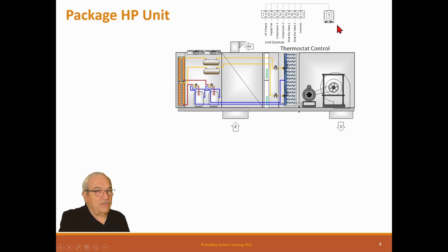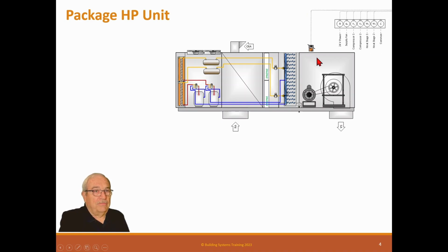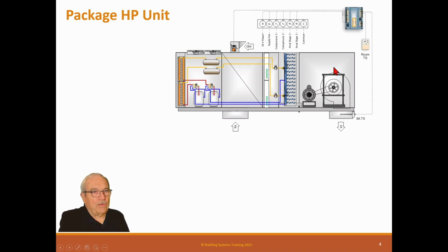And these sub-bases, the thermostat has to know which is which also. Does it put power to it for heat, or does it put power to it for cooling? Because I can't tell you, because every manufacturer might be different. I wish that wasn't so. You can overlay it with a DDC system by wiring the relay outputs to these different points.